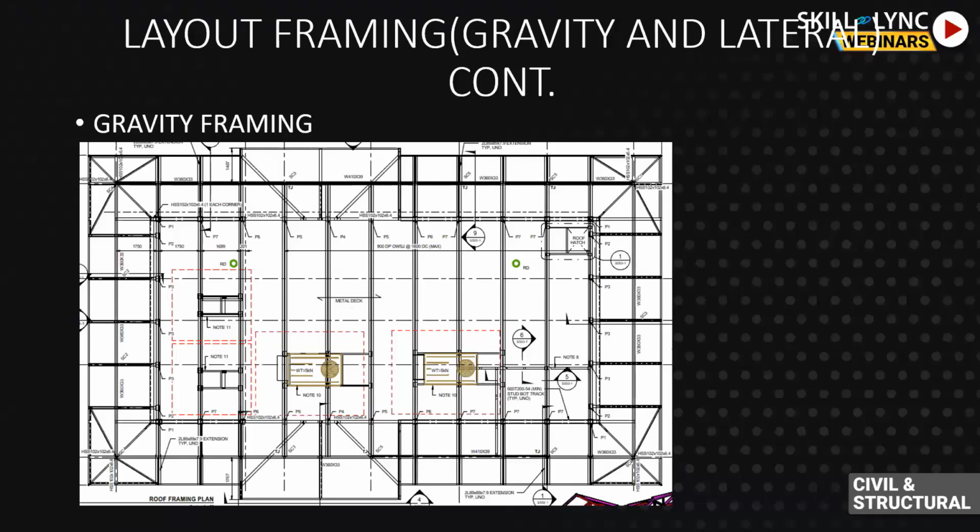It's just a corrugated roof deck made up of steel, pretty light gauge, pretty lightweight. But when you put it effectively, it's good enough to take up some load. So this is again wherein you are using your material efficiently to reduce the cost, to come up with an efficient framing option laid out there.